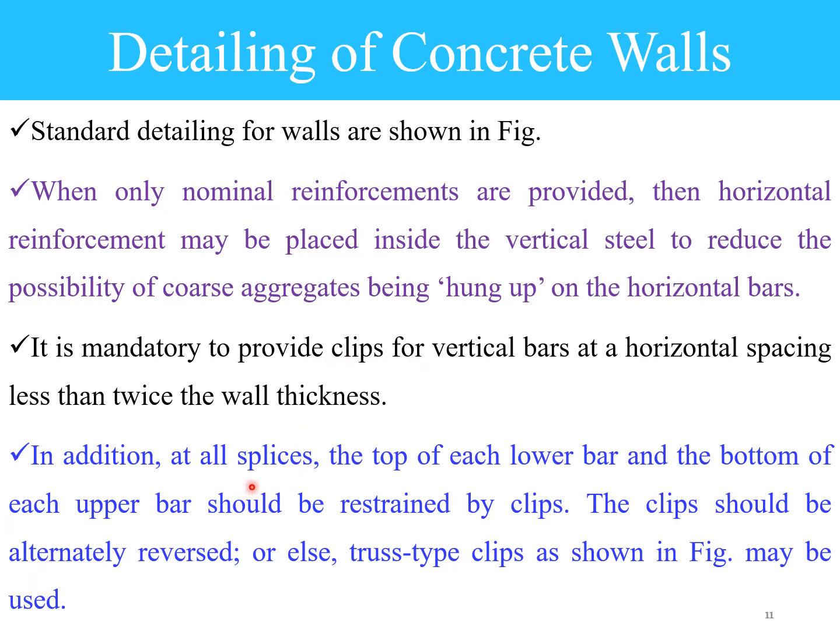In addition, at all splices, the top of each reinforcement bar and the bottom of each upper bar should be restrained by clips. The clips should be alternately reversed, or else truss clips shall be provided, something like this.